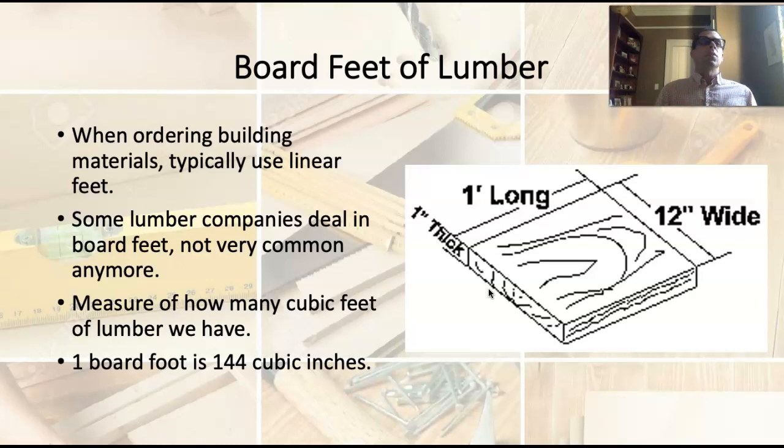So again, Almquist is the place where you're going to regularly encounter lumber that is sold by the board foot. Almost every other place sells by the lineal foot, but it's important to know people use this wrong all the time, especially on Craigslist. People say board feet when they mean lineal footage. So you need to understand what exactly we're talking about.